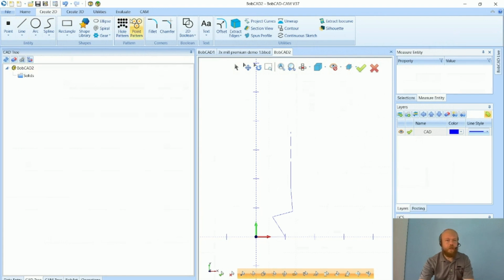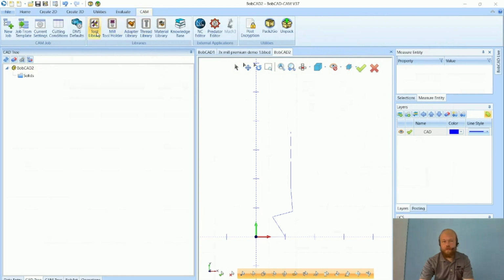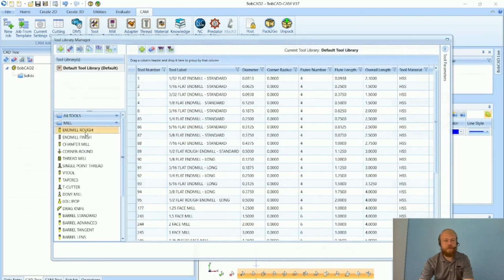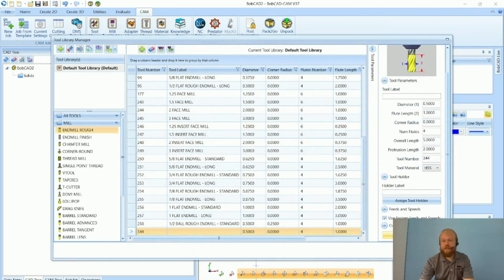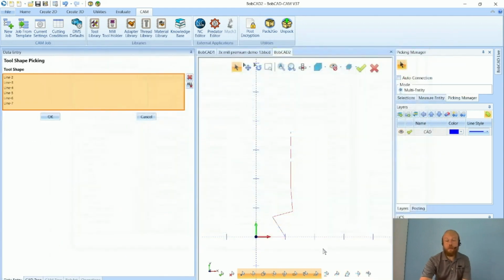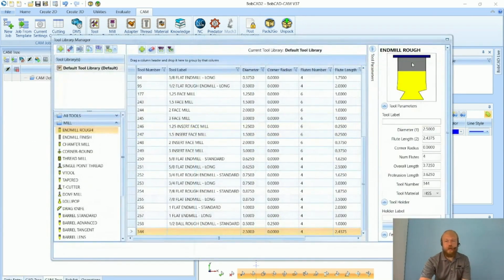So we've got our tool here. We go to CAM, go to Tool Library, and I can go to Mill. I can add a new tool up at the top, and then I can go down and assign tool geometry. I would select this profile of the tool here, and then you can see that geometry of the tool can be utilized for 3-axis roughing and 3-axis Pro operations, other finish operations as well. That can be really useful for 3-axis Pro. Let's see, scrolling down, some of the other features there with 3-axis milling.